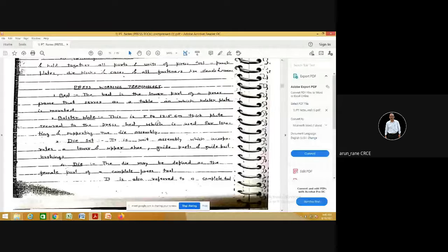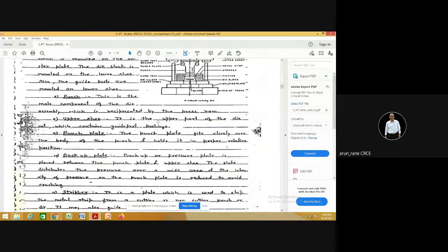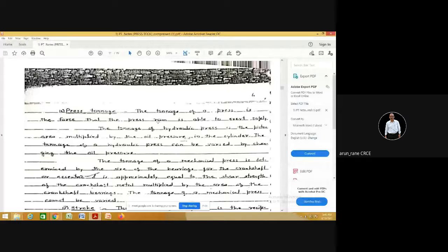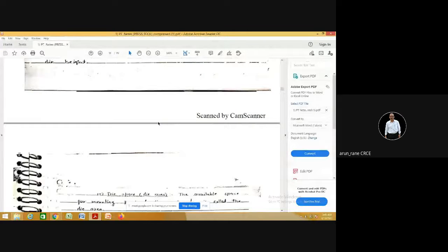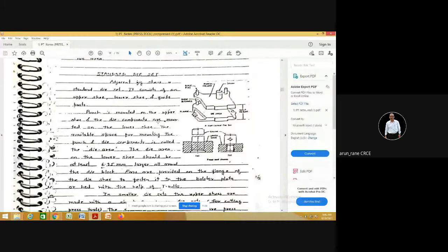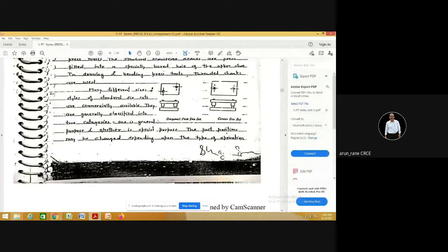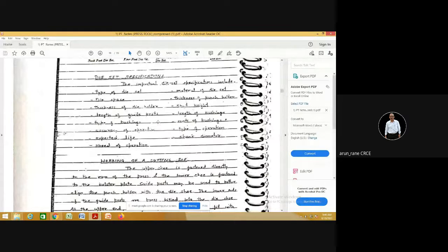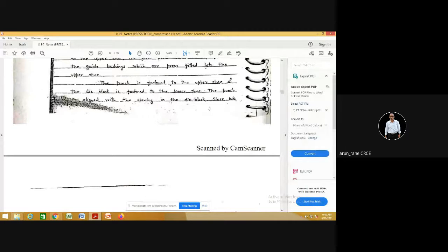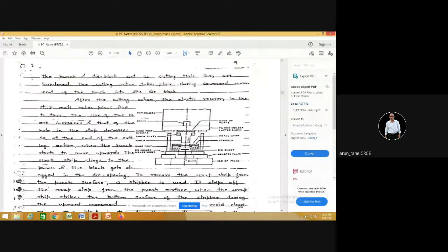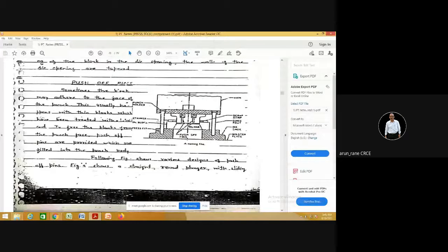So what are the press working terminology, or what are the press parts? If you look at the marking scheme, you will find that there are more marks than your jigs and fixture for the press tools. As there are standard die sets available in the market, which you can procure, that reduces the lead time of the tool manufacturing. If you are getting standard components, standard mold bases, standard guide pins, standard base plates, then your lead time is reduced a lot, right?